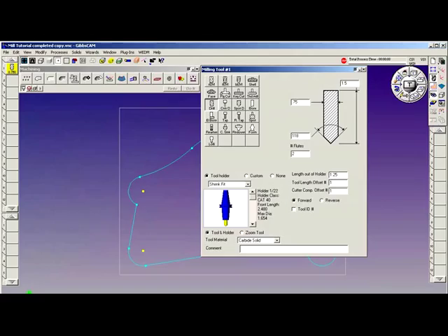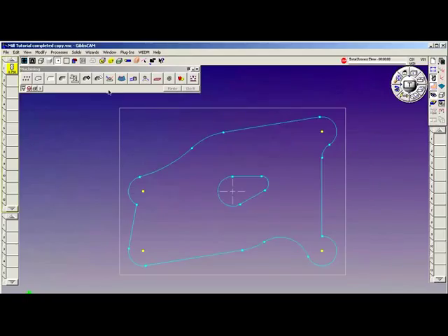3/4 inch diameter, 120 degrees on the angle, 2 flutes, and I'm going to take it out of the holder 1 inch, tool length offset number 1, cutter comp offset number 1, forward spindle direction, and my tool material will be a tin-coated high-speed steel drill. Okay, I'm going to make a comment, call it drill, just for the sake of having a comment. We'll close the dialog, hover the cursor over the tile, and see that it says drill.